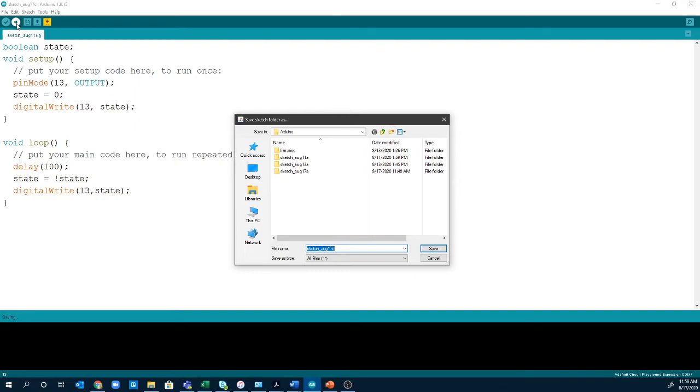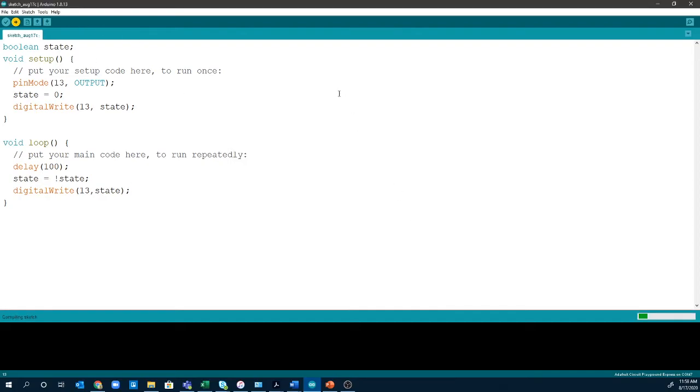This incrementing will happen with every new sketch you create on that same day. Now it's important to note that say a year goes by, you're going to end up on the same day. Therefore, it will just continue in the C, D, E, F progression as you would expect. So for today, I have it set to August 17th, C. So let's go ahead and save that.